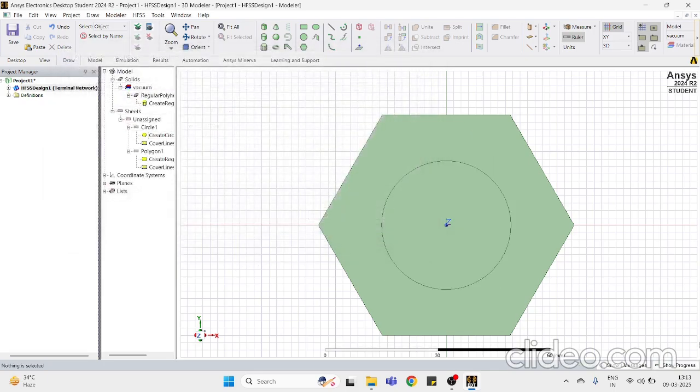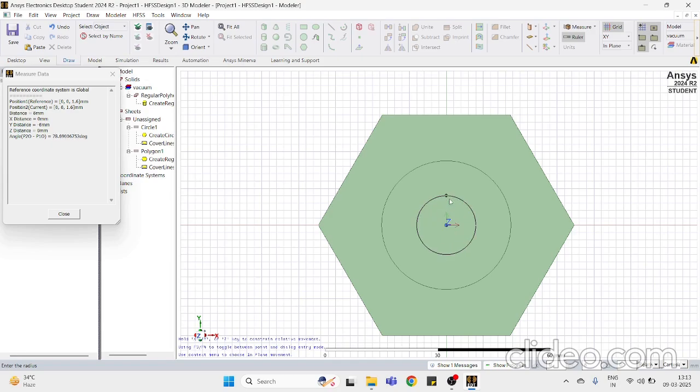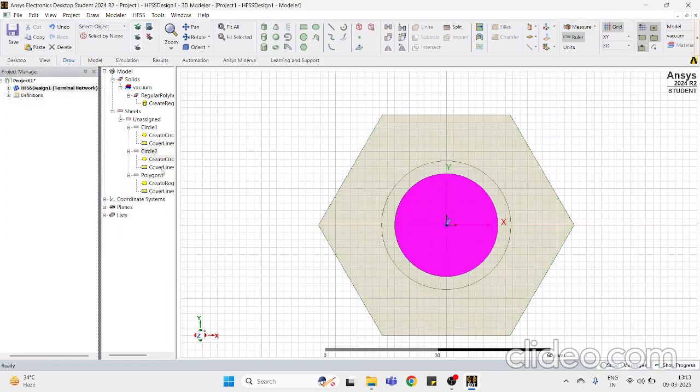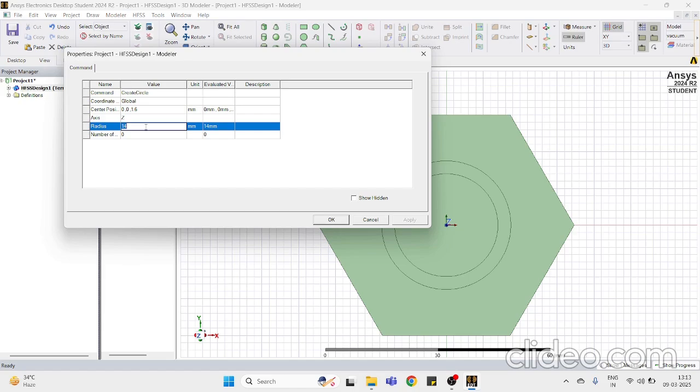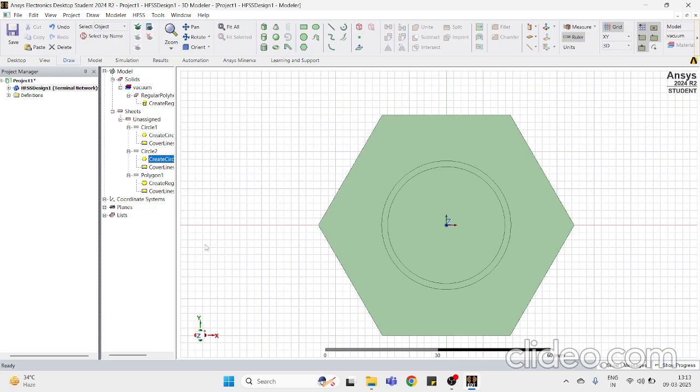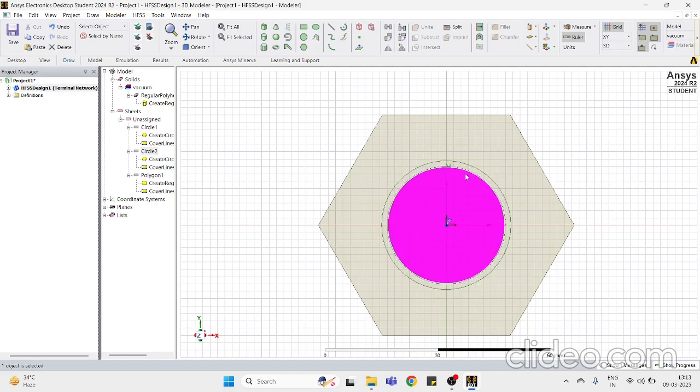Yeah, and I have a 17.52 mm circle, and similarly I'm going to draw a 15.9 mm circle as prescribed by the manual. 15.9, it's taking in mm. Now what I'll do is I'll have to subtract the two circles because this part is what I don't want, the highlighted part. So to remove that, I'm just gonna have to subtract that smaller part from the bigger circle.